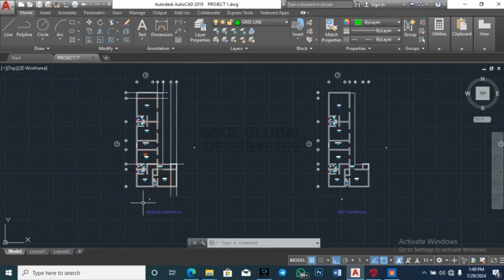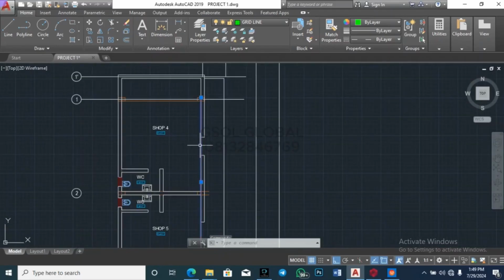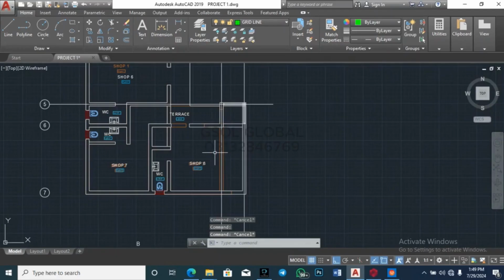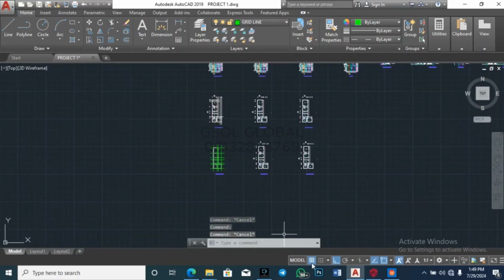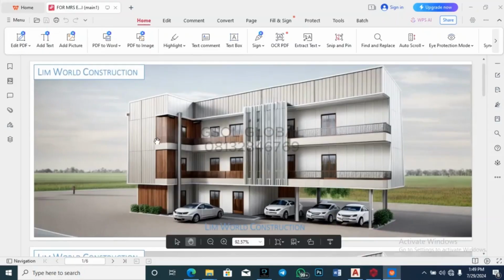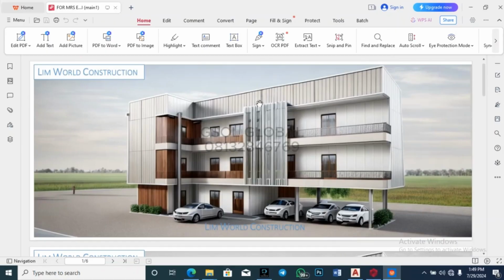This is a wall. This one was actually superimposed, remember? So we superimpose this one on this one. So this is the major wall here. Okay. So now if you go back to the 3D view, you see this place that we don't have any column ranging from the ground floor to the parapet level. There's no column there. All right. This one is just majorly for design, but also acting as a column. So it's also a column, but actually an architectural column. All right, it's doing something there, but we still have to design these beams independently of this column.